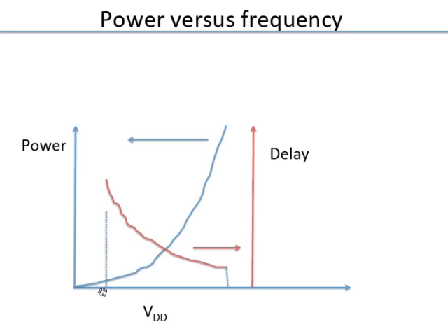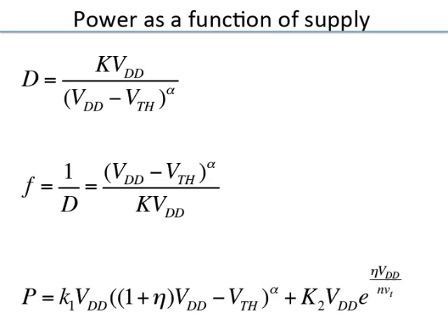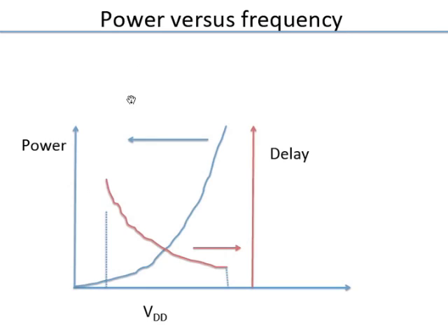Now of course at this regime out here, between 200 to 300 or 350 millivolts, you are in the sub-threshold regime. So you have to be careful. You can't use this equation for delay, because this delay assumes super-threshold operation. So here you have to replace this current I by the sub-threshold equation for the current. So when you plot these kinds of curves, you have to make sure you use the right equations.